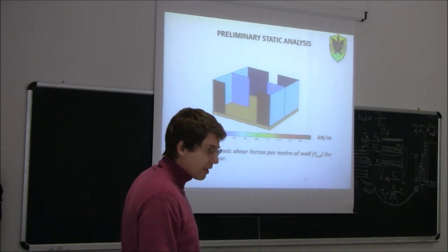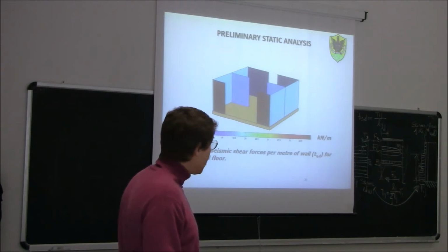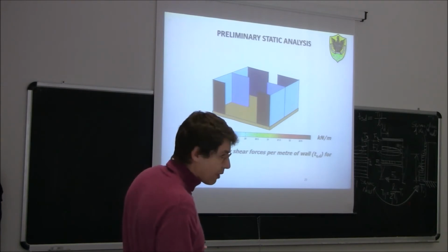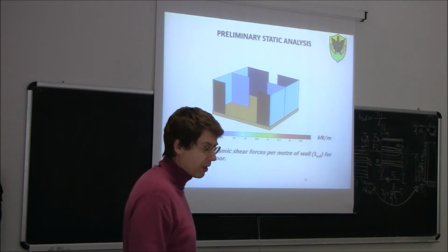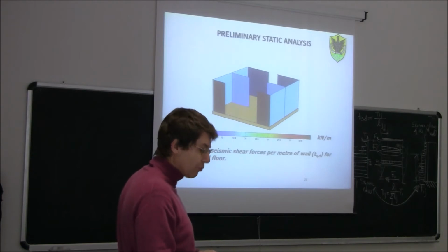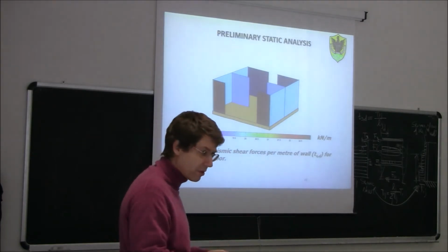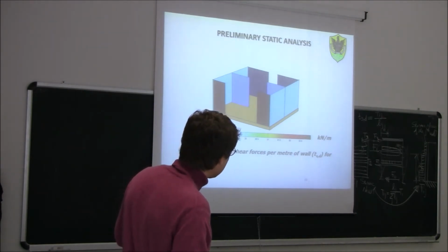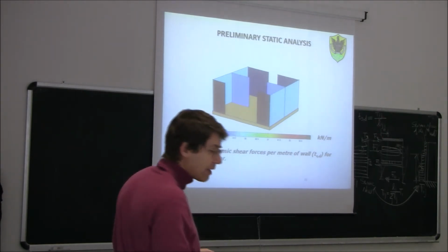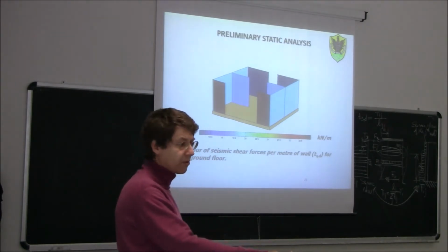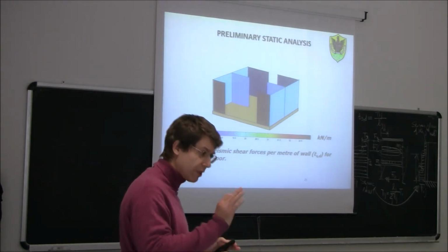Yes. Or we can take it out with this wall? No, because until you use this formula here, you don't know which one is the most stressed one. So you need to do the distribution of the forces among all the walls. Then you divide the forces by the length, and you take the wall that has this ratio as the maximum. And then you design this one, only this. Okay?